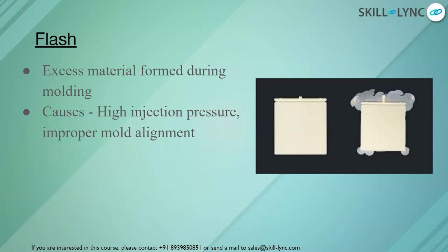How we can avoid it is to make sure that proper clamping is done, proper alignment is there for the core and cavity blocks, and also making sure that injection pressure is adequate.